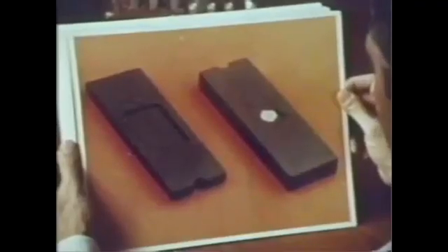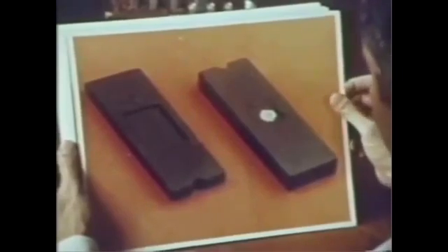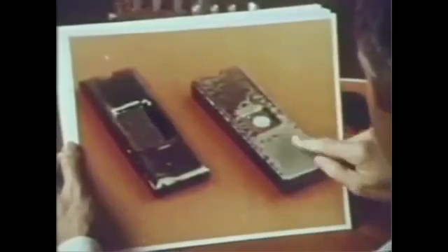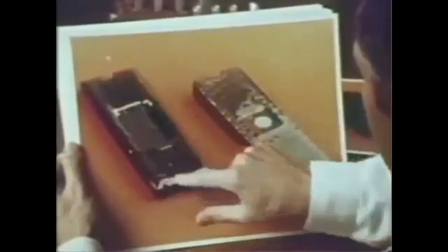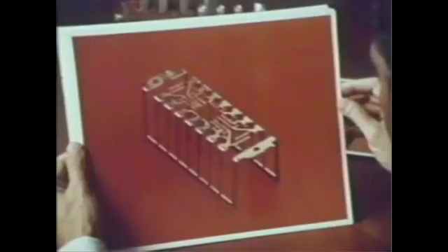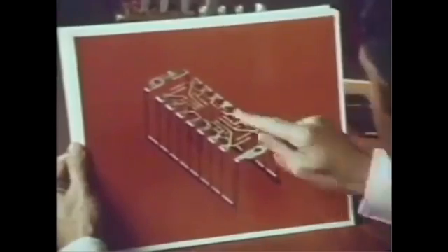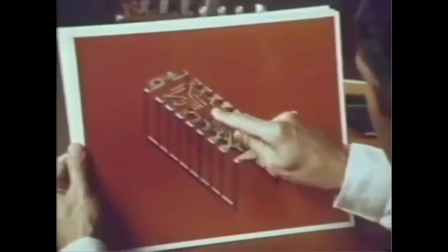You start out with the idea that you're going to build a tasty but inedible sandwich. Here are the two halves that you begin with. Two ceramic parts into which the integrated circuit chip will form the sandwich meat. The two halves are glassed with a material which will form the solder that glues the two halves together later. A Kovar frame has been prepared in advance and cut out to the pattern necessary to connect the chip to the outside world. This Kovar frame will also be placed in the middle of the sandwich alongside of the chip.